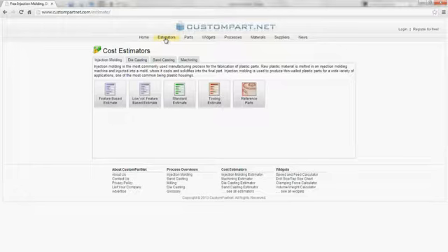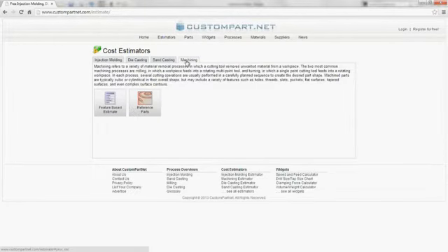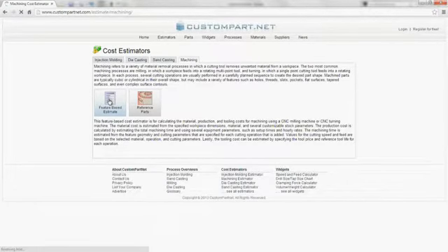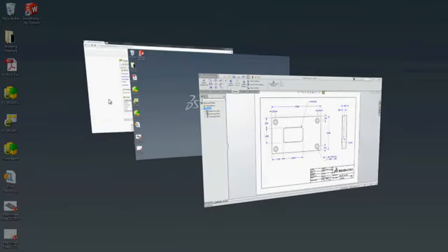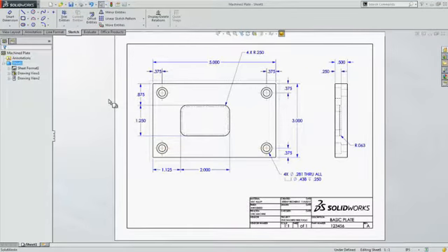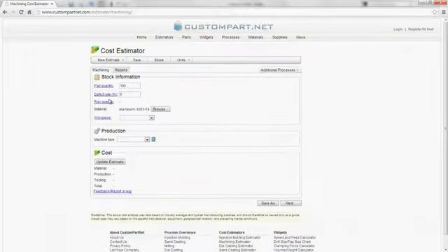They're available for several manufacturing processes from injection molding to machining. Specifically, you can calculate the cost based on the features in your part. We happen to have a very simple example in SOLIDWORKS with 4 counterbore holes and a pocket, and require a total of 5 of these parts to be machined. The first step we need to do is provide a quantity of 5. You could further provide the expected defect rate and run quantity, but in this case there will only be one run with the expectation that no defects will happen.